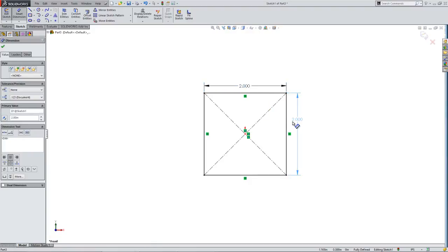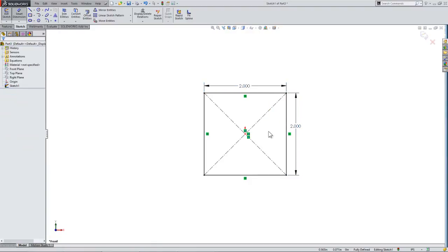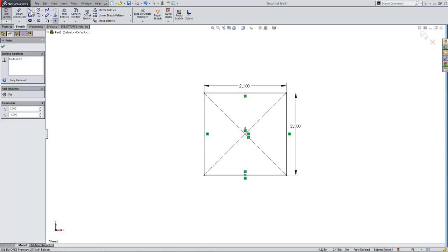The things to know that are important in a weldment profile: the location of the origin is going to serve as your default pierce point. So wherever you want to typically run your profiles from, you want your origin to be there. Corners and endpoints and other points on the sketch will serve as alternative pierce points, and so we can place one there with a point tool.